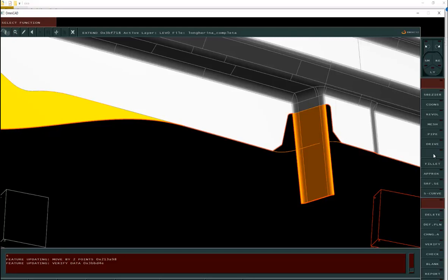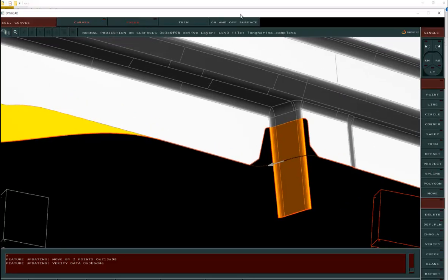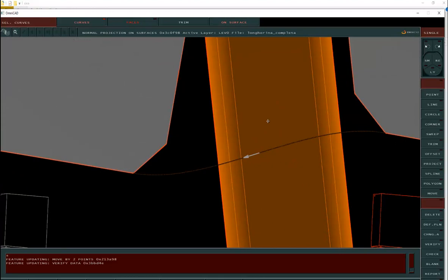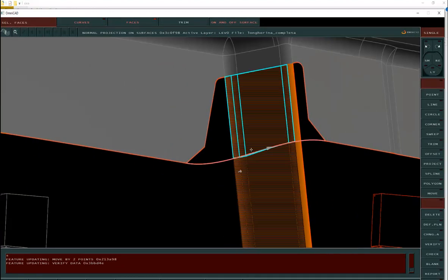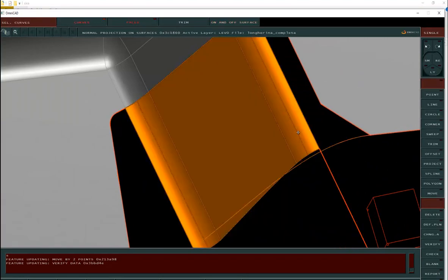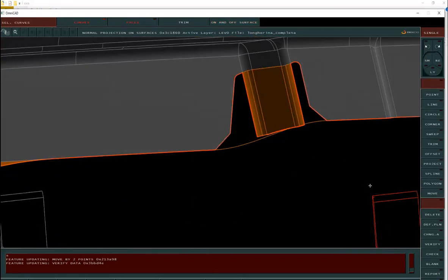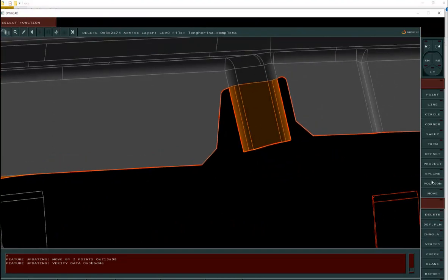Here I can use project, surface normal, this curve, and cut this surface. Same right side external part, and now I will delete this curve and use in die tool fill hole and tangent surface curve. You select from this profile to this other profile.